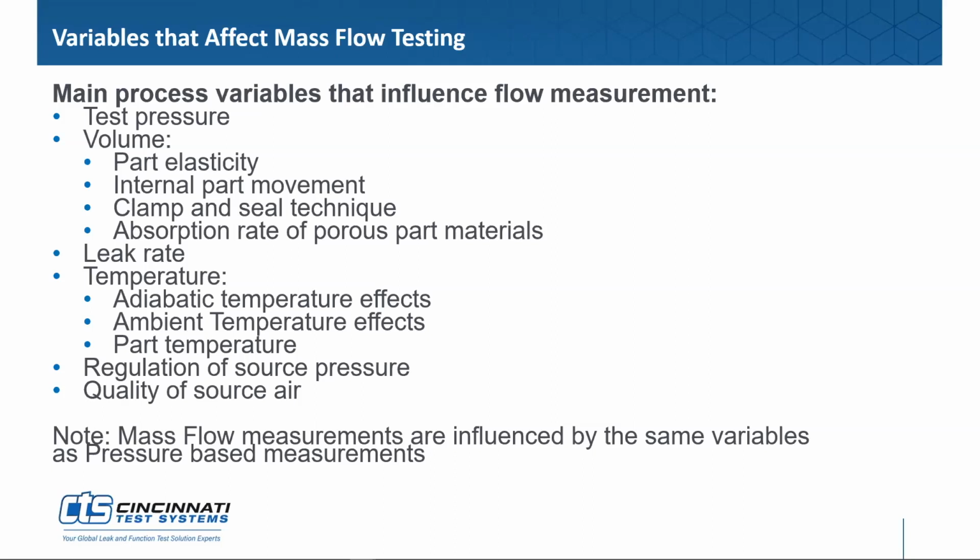Yep, where it's a comparison of two measurements. The key to pressure decay testing and mass flow testing is all those variables that affect pressure decay also affect mass flow testing. The difference is that mass flow testing isn't as affected by the size of the part you're measuring test to test. If you've at least set up your test cycle time for the largest part variance that you may be testing in your cycles, you don't need to worry so much about part size volume differences during test.